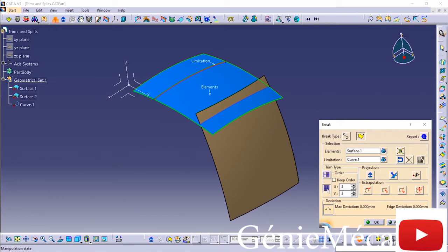And then next is what's called trim type. You have a couple of different kinds of trims. One of them will trim the surface and leave the control points as they were. And you also have surface trim, which will recompile the control points. Basically, it'll take this, remove this portion, and that surface is now trimmed back to this edge. There's no history or anything beyond that boundary. It recompiles those control points. So this may cause your surface to change shape drastically if you don't have enough math, if the orders aren't high enough to fulfill those requirements.